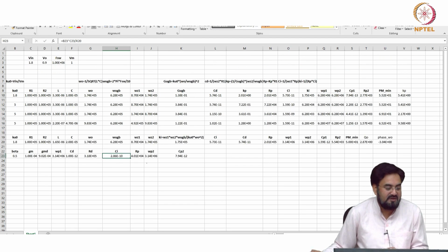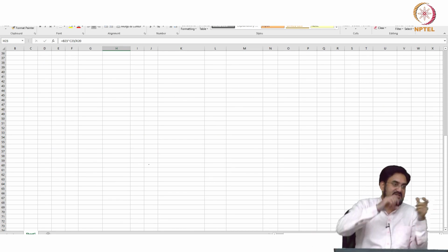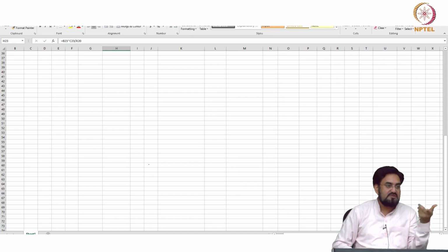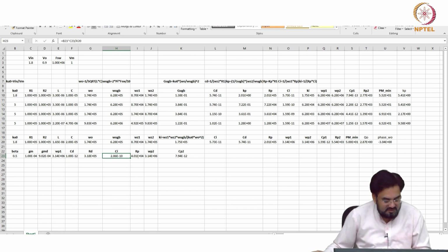That capacitor, we already saw in the case of GM when we designed the PI, was much larger because we are choosing a higher GM. If I lower the GM, let us say I make it 10 instead of 110, then this will become 28.6 picofarad, but then the issue will be the offset. So that is why we do not choose too low.